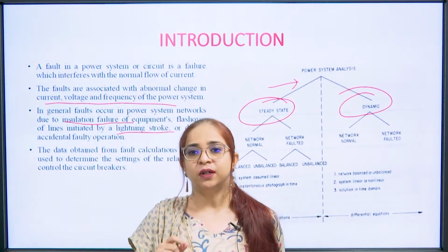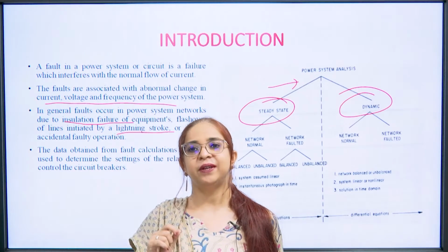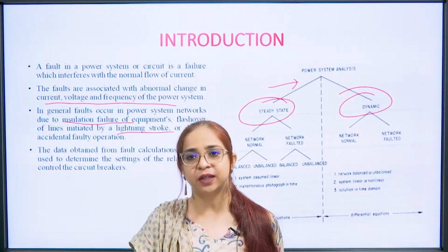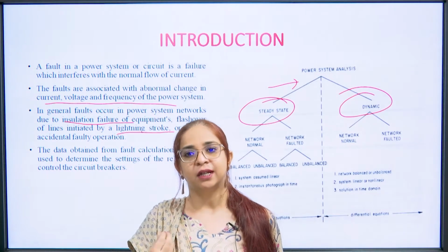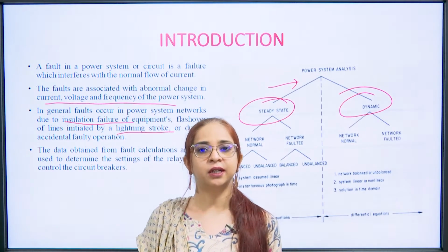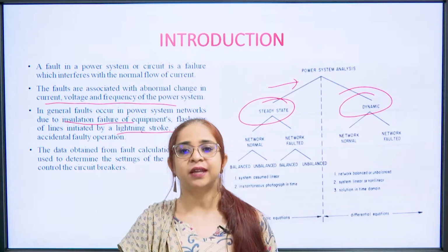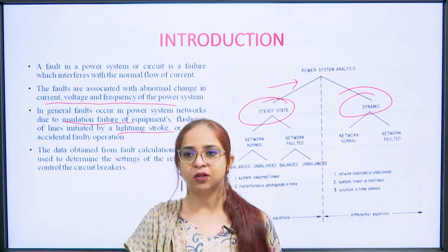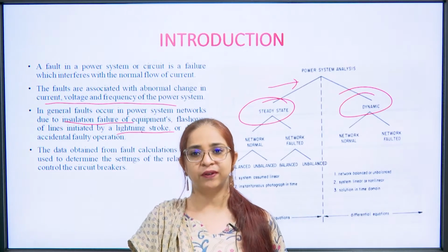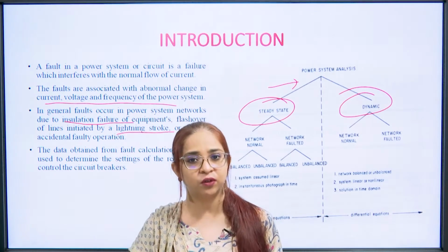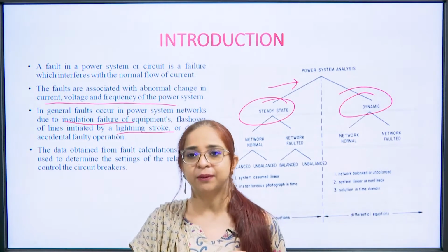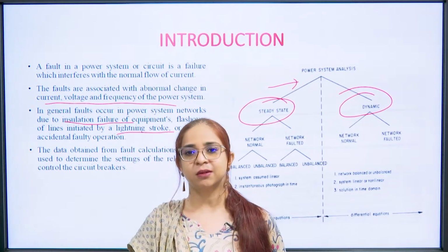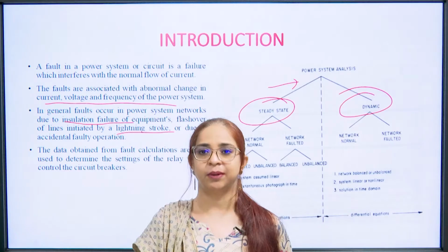As we know, the term steady state means we have reached a condition where the network is in a steady state, and then whatever we are trying to analyze comes under steady state analysis. And dynamic means change. So when something is changing, at the time of a transient or any change in load, major shifting of load, such things happen at that particular instant when we want to study the entire power system and its behavior, then we say it is a dynamic analysis.